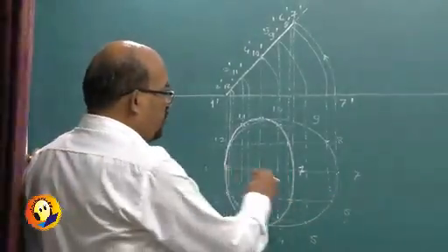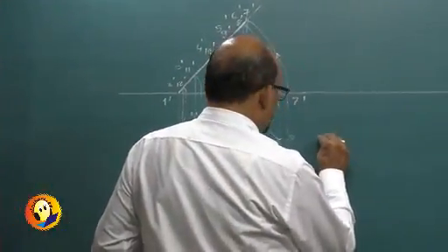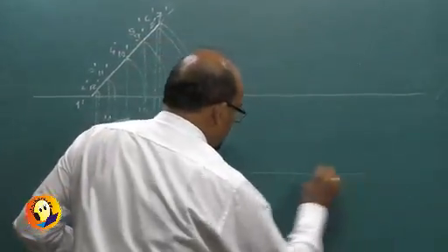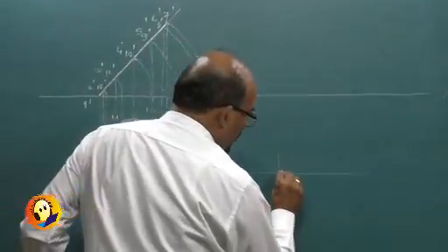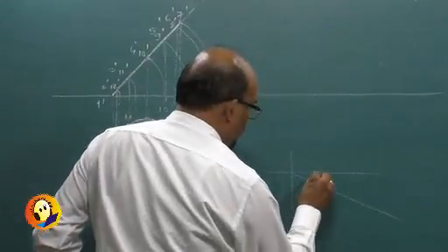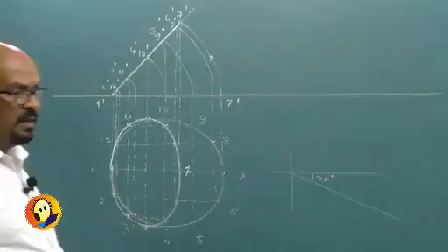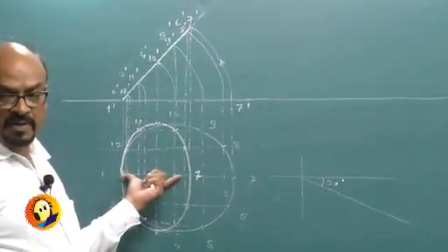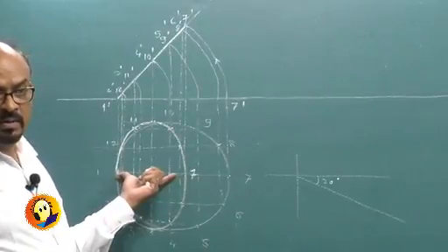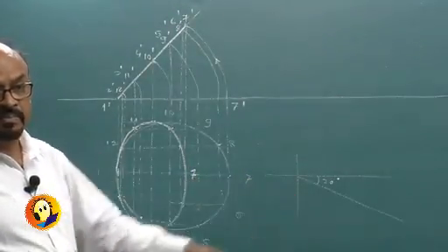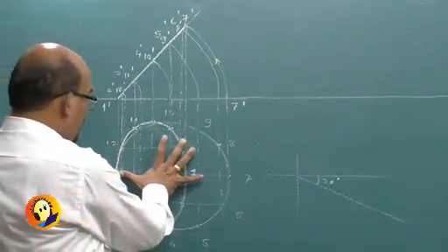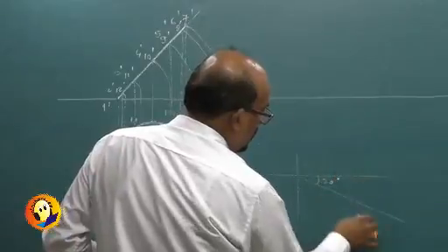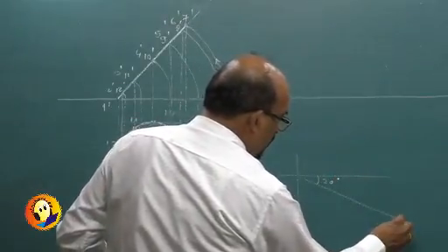Now while redrawing this figure, first of all, if that diagonal is to make 20 degrees, I should take 20 degrees line, and then onto this I should mark 17, but problem is that 17 is not the true length, whereas this is given as angle with VP. So we are required to take the actual diameter, true length, and cut the arc. So could be here.